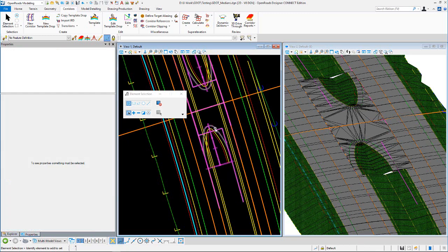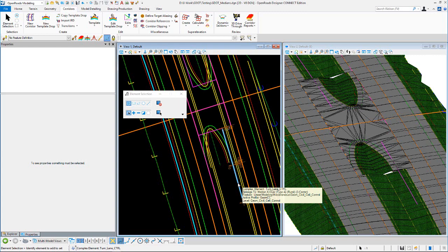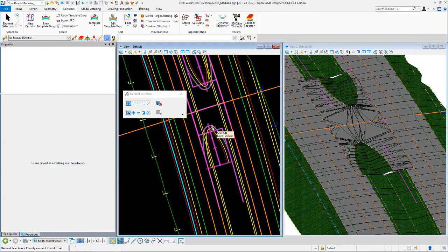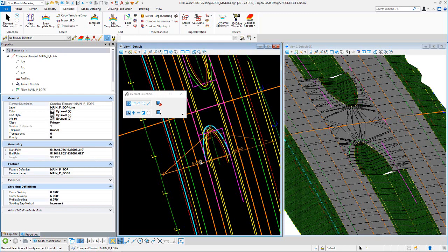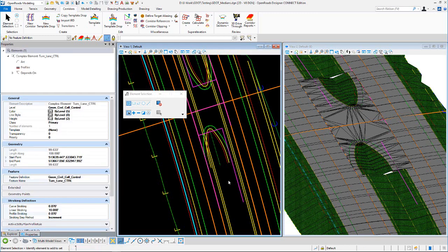If you need to change this radius and it pushes beyond those purple lines there, the cell is going to fail. So if you have a situation like that, and I don't think you will, it's possible you may need to extend that 100 feet a little bit longer if you have a real flat radius there that you want to use. But like I said, I don't think that's an edit you'll have to make.